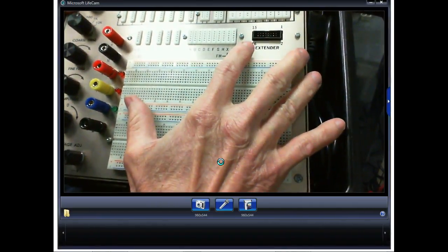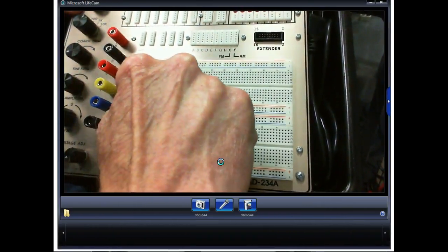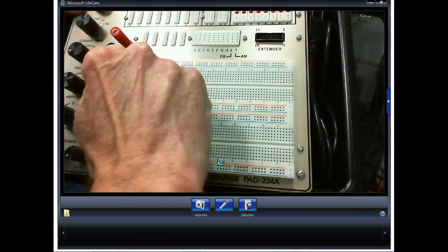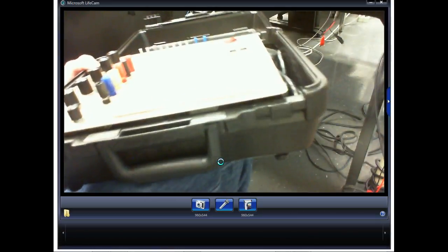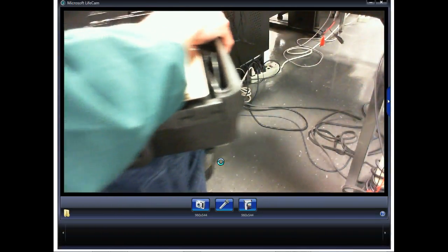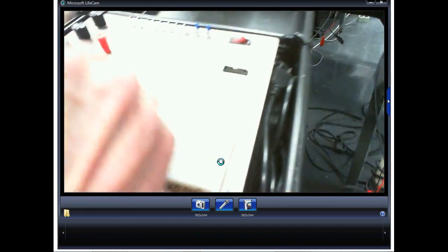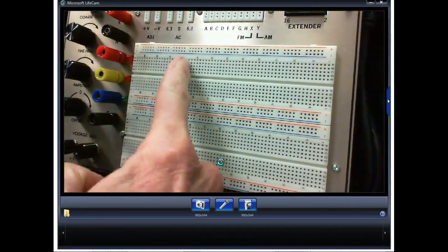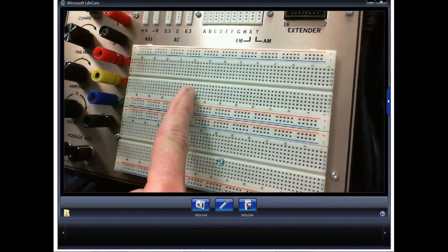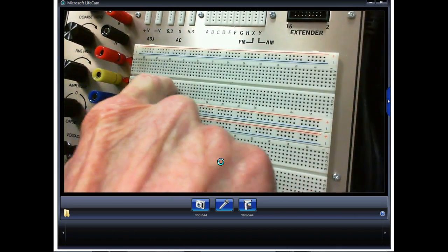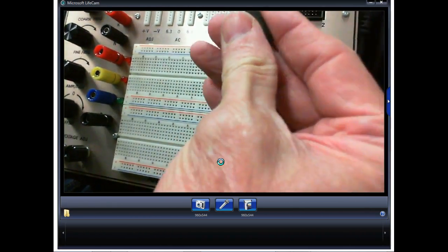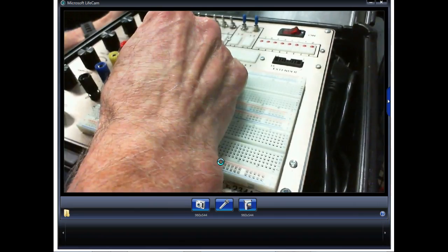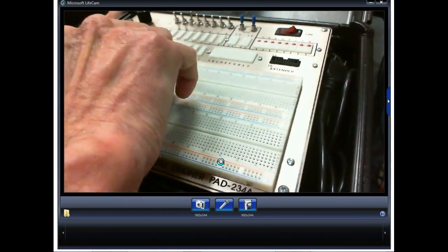You know how the breadboard works, right? You know there is a break between here and there. So where do you think these ICs go? Well, the ICs are going to go across this trough right here. See the trough right here? Everything on this is connected together. Everything down here is connected together. But it doesn't make a connection to the trough. Why is the trough in there? Well, the trough's in there so I can come up here and put these ICs.